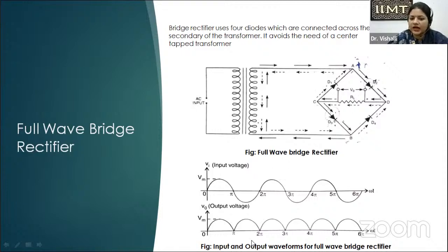So we will be getting the output voltage. This is the output waveform which is represented. Vm is the maximum amplitude of that voltage. So this is the output waveform which we obtained in the case of the full wave bridge rectifier. Also, this output will contain ripple because it has an AC component, it can be clearly seen, but this is a unidirectional flow. And after the rectifier circuit, this output is fed to the filter circuit. The filter circuit basically removes this waviness.